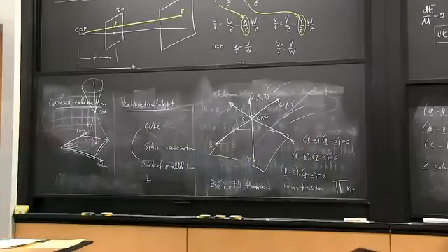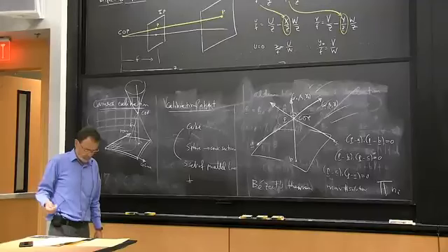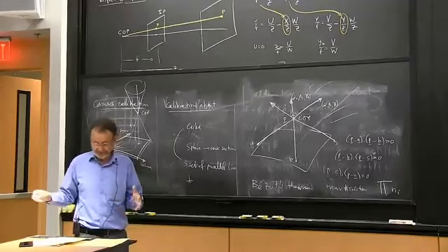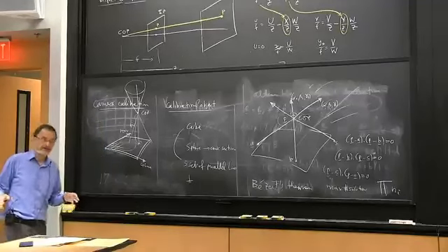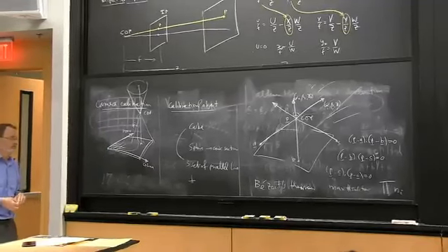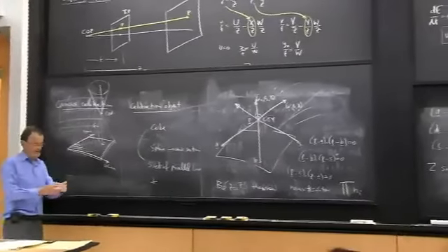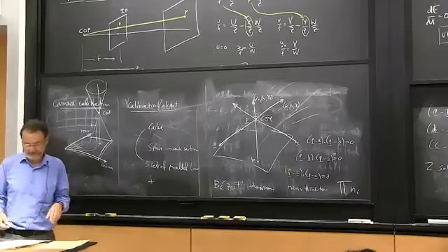Now, if lenses were perfect, that would be it. So this would be it for camera calibration. And we'll talk more about camera calibration later. Lenses have radial distortion, and there are reasons why people don't completely get rid of that. So actually, in practice, when you do real robotics camera calibration, it's this plus the radial distortion parameter. So, okay, that's it for today.